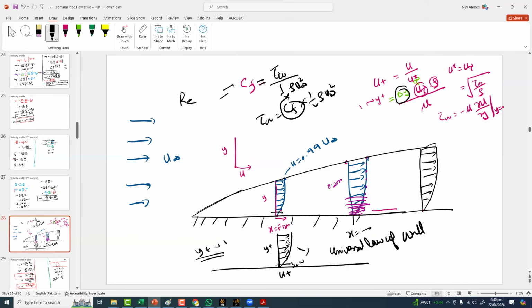So, sir, the point I got from your talk is that y plus is all about external flows. We calculate this value for external flow only, not internal. Internal flows also have y plus and a boundary layer. So internal flows are also affected by y plus values, definitely.